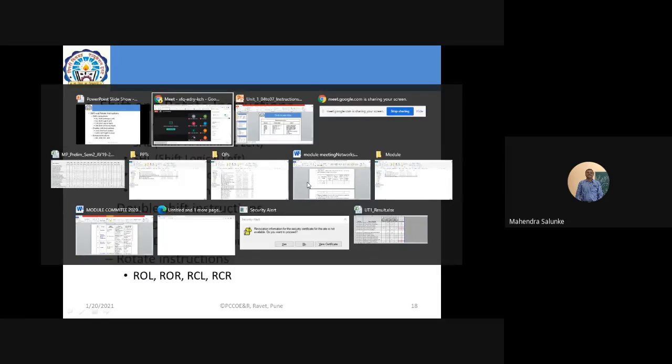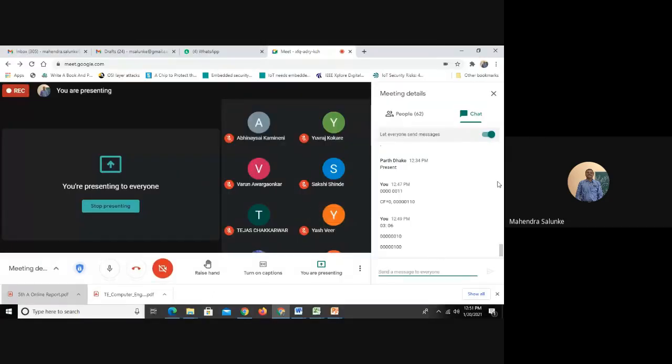Getting this? Here, I will give you one example. Say I have the number 1100 0010. This is the number which I am shifting towards the right side, and that is a logical shift. So for logical right shift, only 0 is getting entered on the left side.